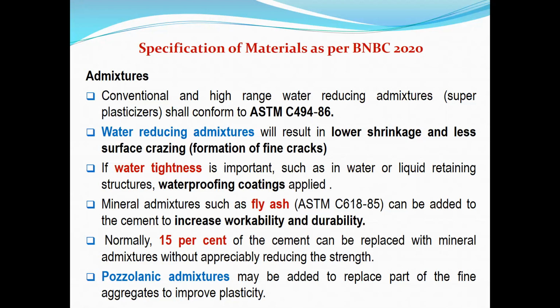But you know that if you use water, then the reaction between the cement and water takes some time, and subsequently shrinkage and other issues may come up. So to reduce the use of water, you can use water reducing admixtures, so that you don't have as much water, but with the use of admixtures, you get the functions which water is supposed to do.